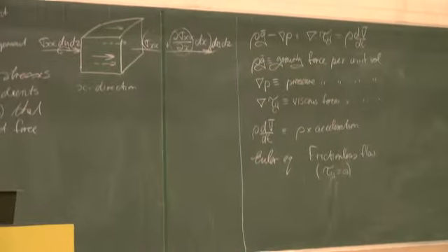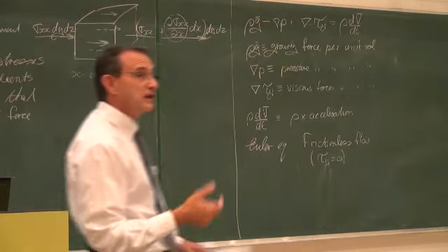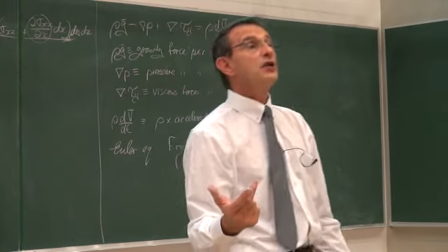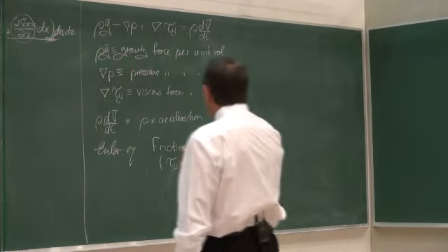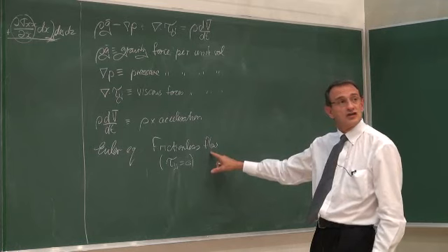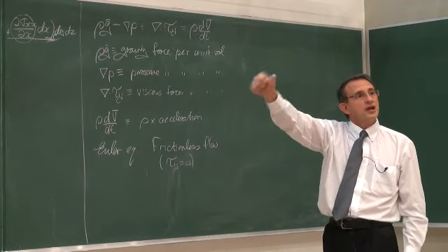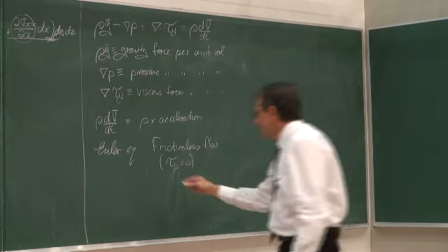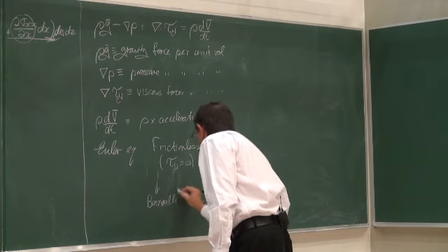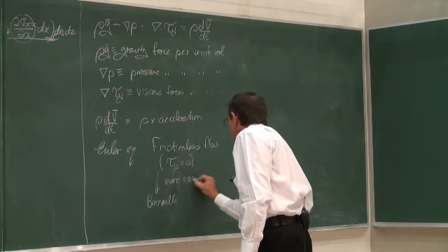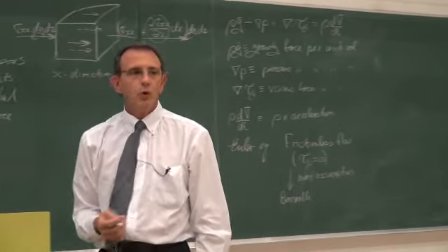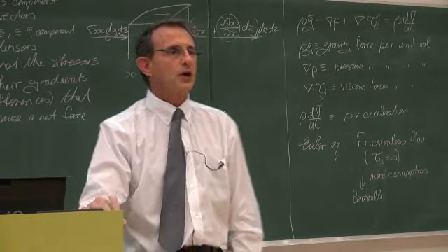Now the Euler equation is an important equation because it feeds into another equation. Can you remember which one? The Bernoulli equation. If we make the assumptions that all the stresses are equal to 0, so it's frictionless flow, and we say it is incompressible and 2D, then from there it follows to the Bernoulli equation. So with more assumptions. The Bernoulli equation is the equation with more assumptions than any other equation.